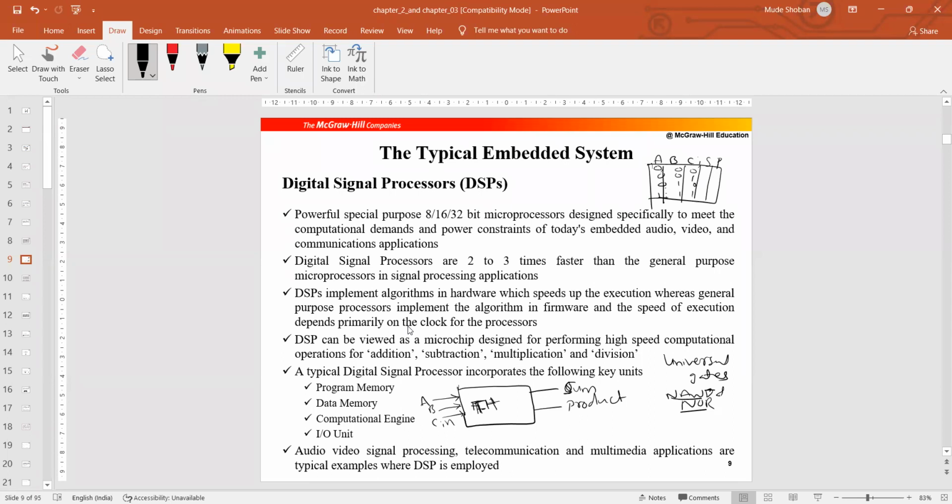So sum 0 plus 0, 0 plus 0, you can add this. So you will get this. So adding this, you get a sum and carry. So based on the truth table, sum and the product, you have to draw the K map. It is an 8-bit, no? 8-bit. So you have to use the K map, right? You can use the K map, A and B, C in. You can map that and you can simplify the Boolean algebra.